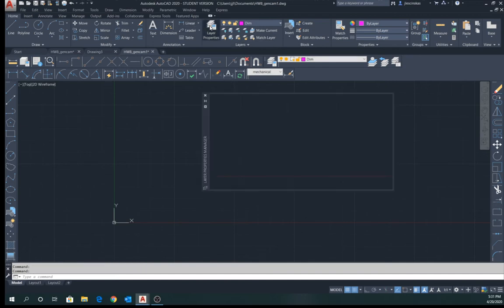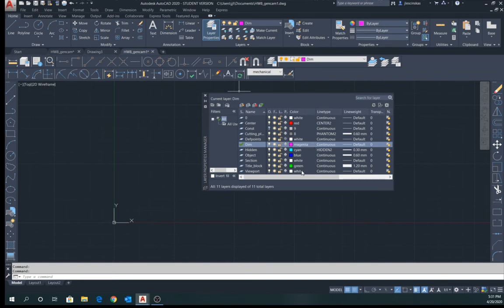Now I do need to add one additional layer. If you look on page 7.9, if you compare all the layers that are shown on page 7.9 to the layers that you have here, you'll see that there's one layer missing, and the layer is title block lettering. The title block lettering is exactly the same as the title block, in the sense that it's green, except the title block lettering actually uses the default line weight instead of this 1.2 millimeter thicker line weight.